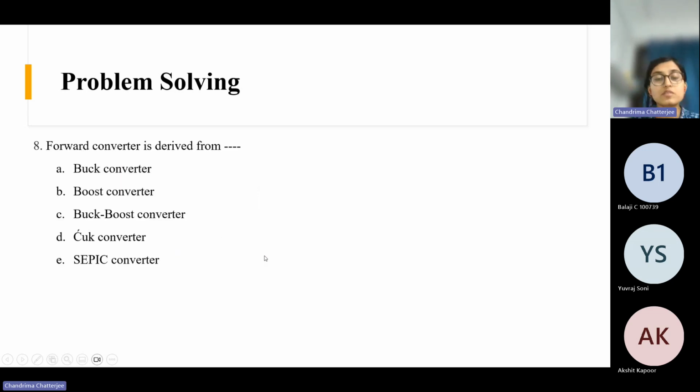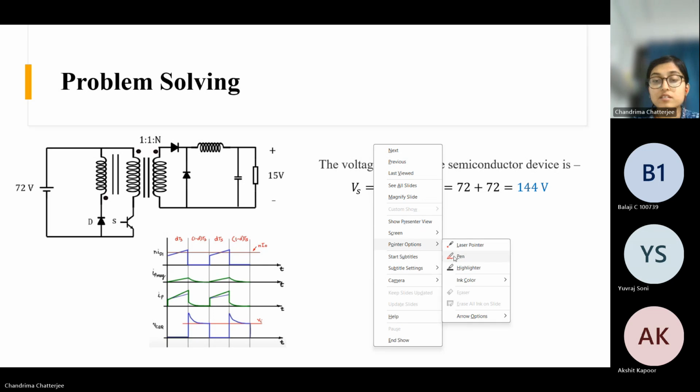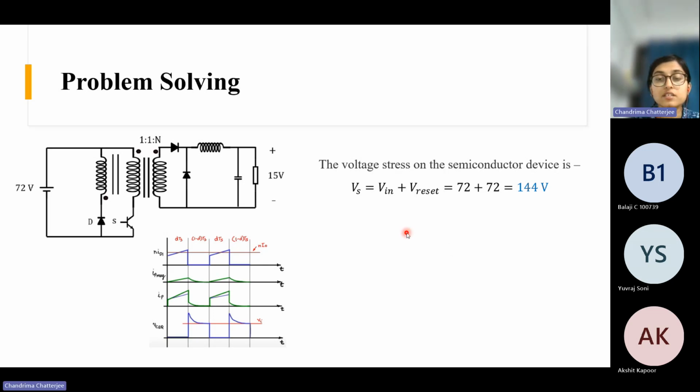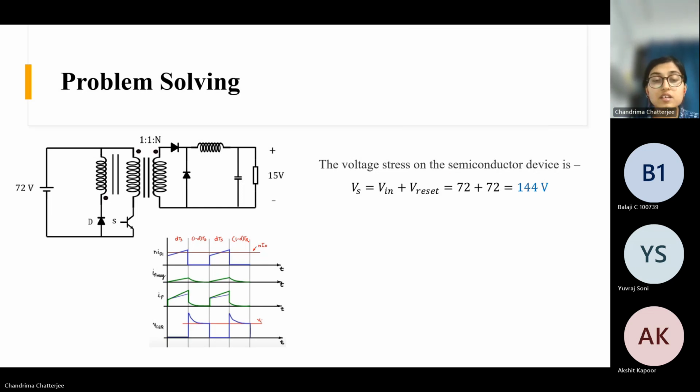So this is the same waveform, the core resetting part here. Okay, so the operation is the same. Whether you use a lossy core resetting circuit or a lossless core resetting circuit, the point is you need to reset the core flux. Wherever the flux is starting, it should get back to the same value before starting the next cycle. That is the point.